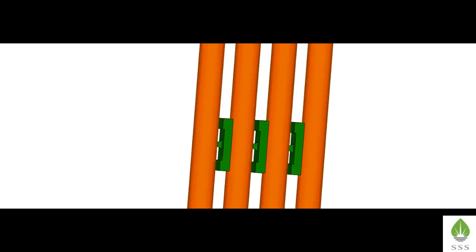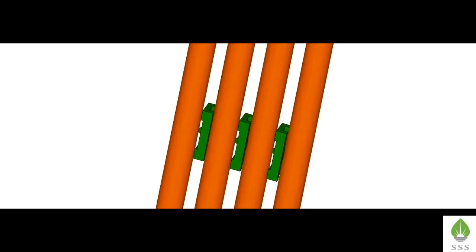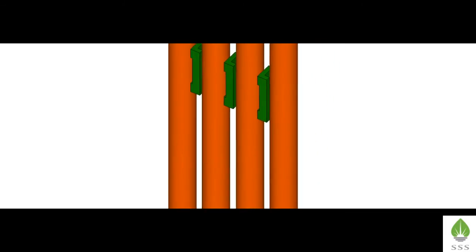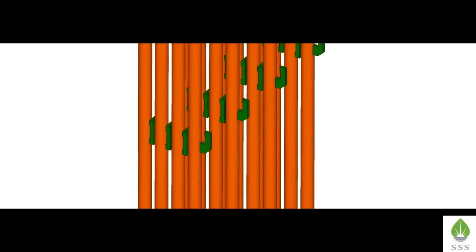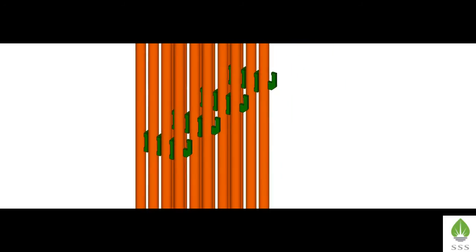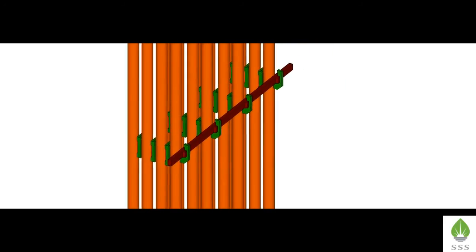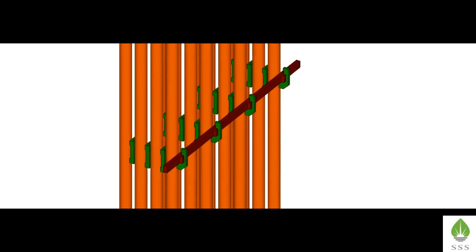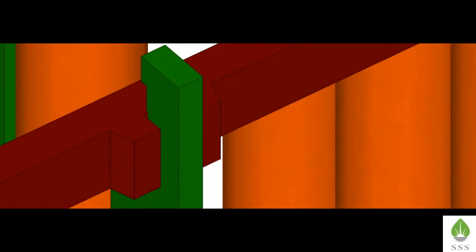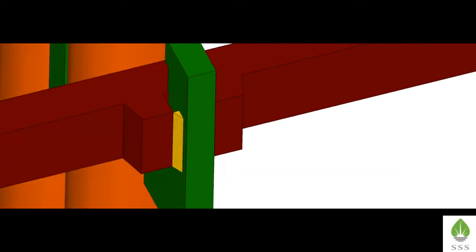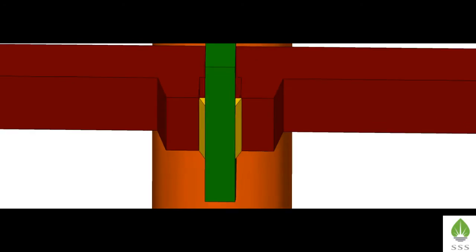Primary superheater vertical coil consists of 4 tubes and the pitch between these tubes is maintained by these separators. These separators are provided at top and bottom portion. The end of the tube is provided with anti-vibration attachment. Lift the same set of another vertical tubes. Insert the rectangular bar between the anti-vibration bar attachment. The rectangular bar is welded with the anti-vibration bar attachment.